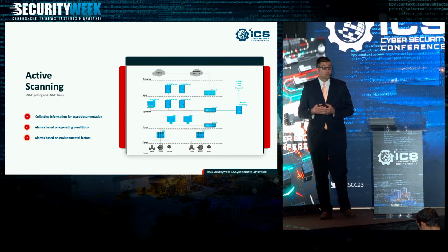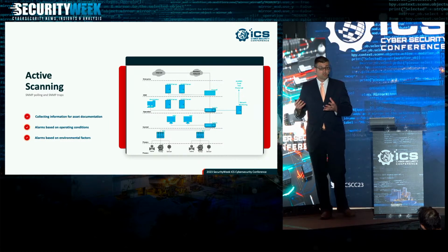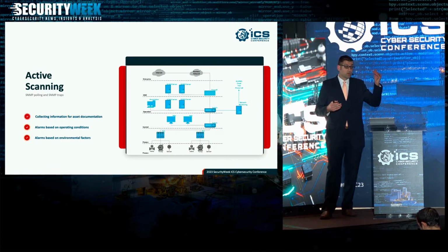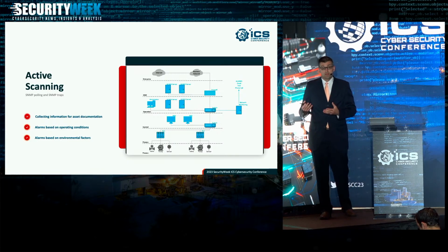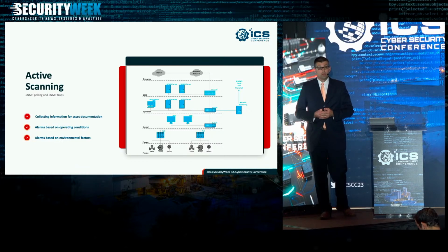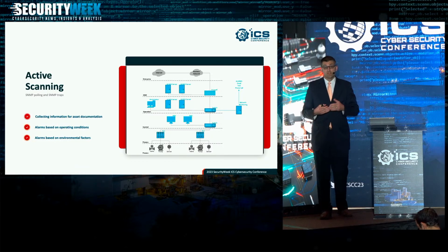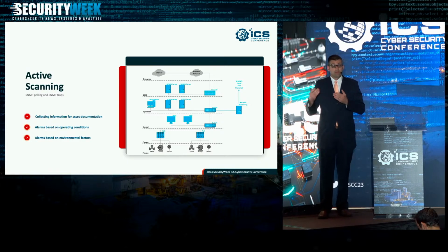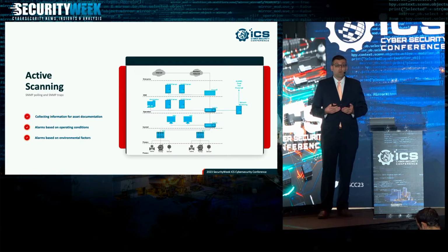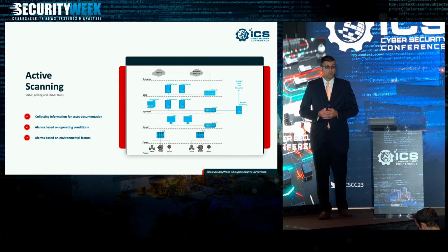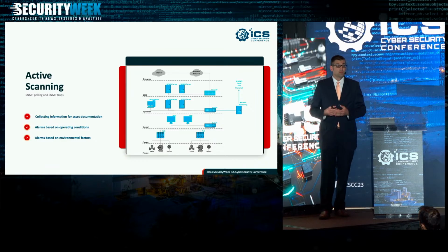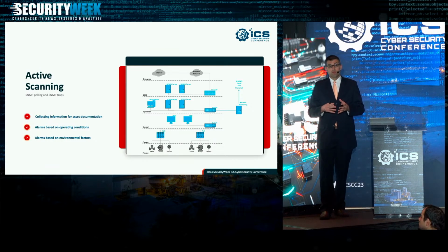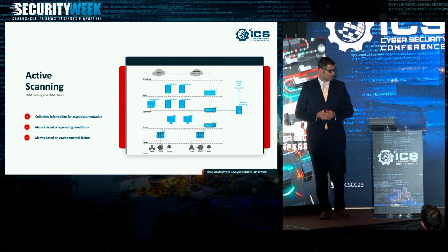Typically, servers, rack mount switches that expect environmentally controlled conditions, they'll reach a threshold where they shut off. So if you want to bring down the SCADA system, or if an attacker wants to bring down that SCADA system and they can shut down a central AC system, if they can cause that server room to heat up, then they can force a shutdown. So we wanted to be aware of what's going on in the environment in that room. Are temperatures rising? If so, we need to get somebody out there to look at it, to get that AC back online, to get portables in place, whatever it needed. That way we could make sure that our system stays up and running.